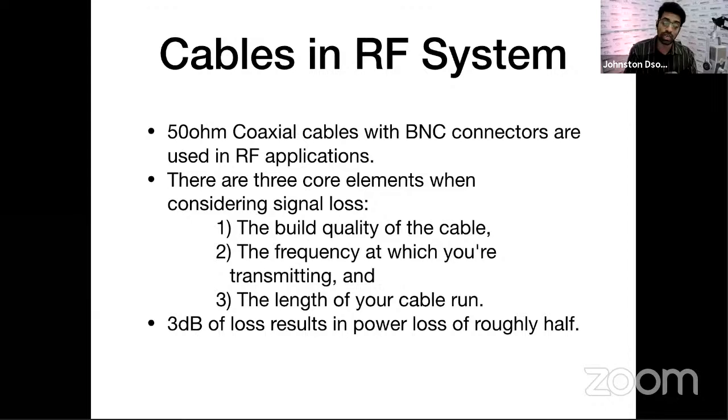Okay, do not use unnecessarily long cables. Say your microphone receiver rack is in one place and the antennas, you need to place them like 5 feet away. Do not use a 100-meter cable for it. Use a cable that is probably 5 or 6 feet, so that you don't have unnecessary losses in the cable. Okay, because that's just a waste of power. Then any problem, cables are usually the last thing you'll go and change, because we don't suspect the most common problem.